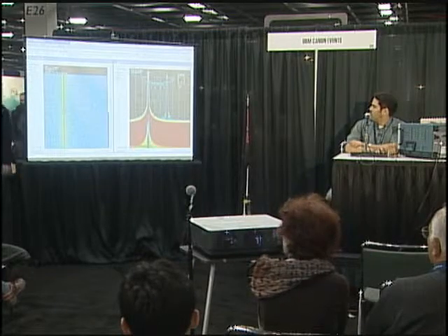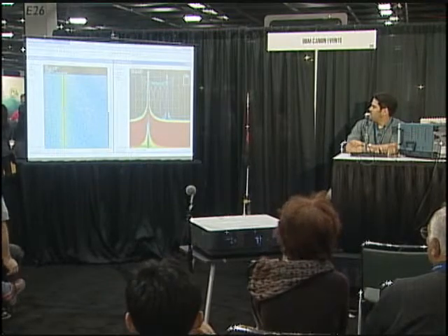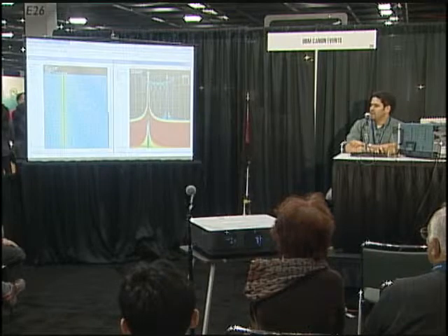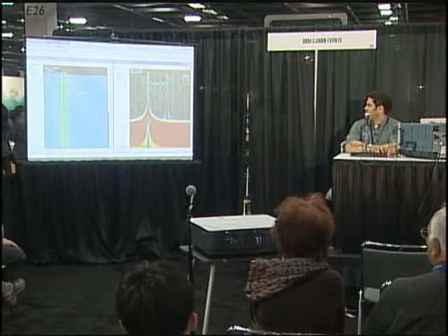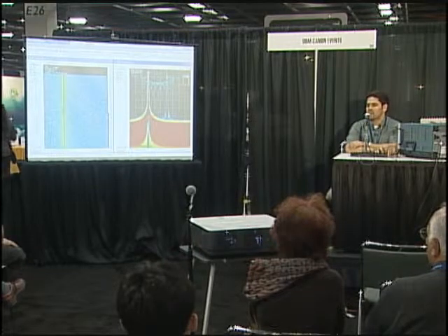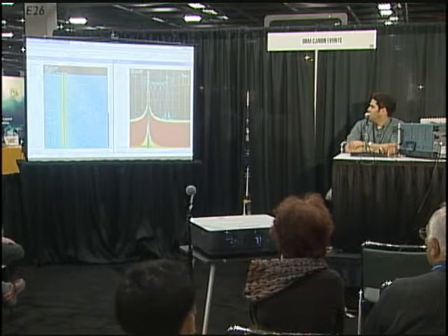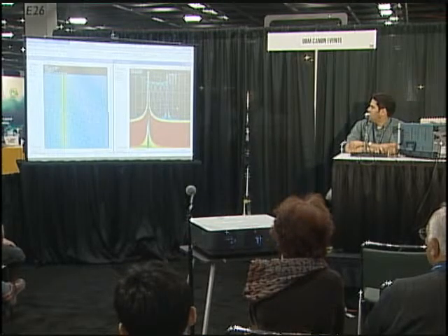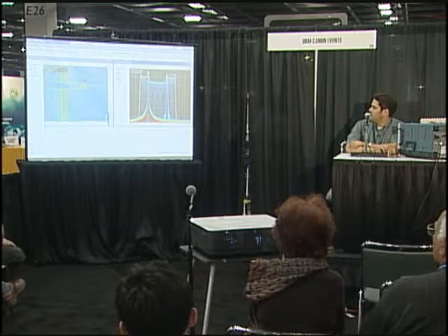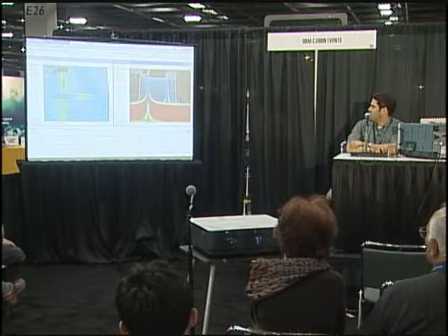And to do that, we're going to use this feature called trigger on this. And what it does is it gives me this little box that tells the analyzer, make this acquisition whenever something gets into the box at 300,000 updates per second. The minimum transient that we can capture, the fastest, is about 5.8 microseconds. So I'm going to move this over here. And there we go. Now we're making the acquisitions, in this case, 1 millisecond acquisitions, every time that the signal goes into the box.